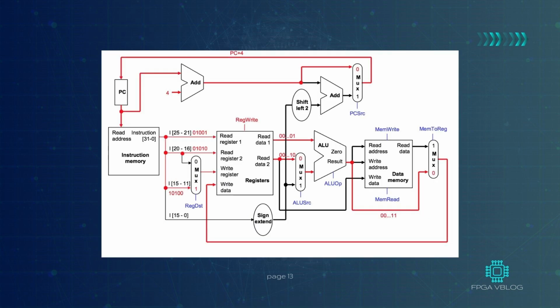This shows processor architecture: instruction memory, program counter, registers, ALU, and data memory. Instruction memory holds the machine code of the given program to be run. The program counter points to each instruction to be executed. Registers hold the data until it is used by the ALU. Data to be processed can be loaded and processed data can be stored in the data memory.